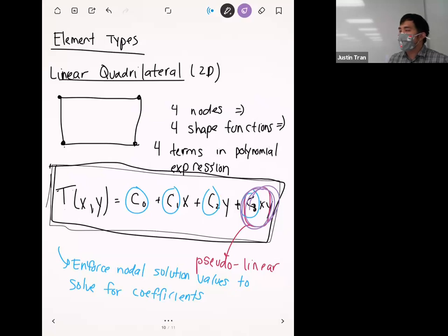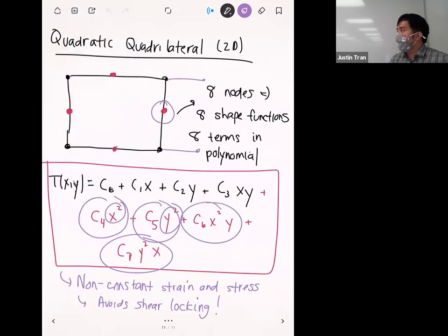And so I've talked to several people in this class who I think have tried to do the activity on their home laptops, and they just haven't been able to produce a hex mesh on anything that we tried. And it's okay, if you don't get it, it's fine, because again, you're using quadratic elements. And so with quadratic elements, you really don't have to worry about shear locking at all, whether you're using triangles or quadrilaterals. But if you are using linear elements, try to use the box type elements if you can. Okay. All right, any questions on this?